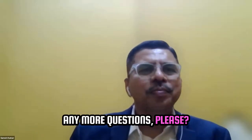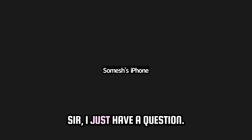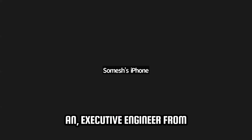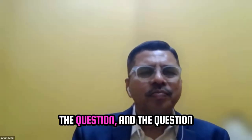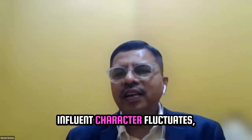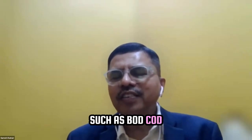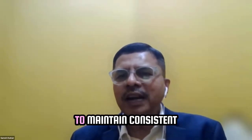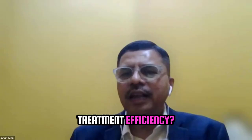Any more questions, please? Suresh sir, I just have a question. The same question was asked by an executive engineer from CPWD. I am just typing the question and it is on your screen right now. In cases where influent character fluctuates, such as BOD COD variation by more than 30%, how do we design buffer capacity to maintain consistent treatment efficiency?